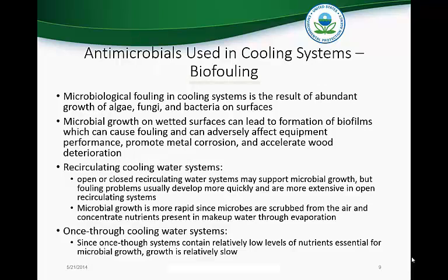We're going to talk a little bit about biofouling in this slide. Microbiological fouling in cooling systems is a result of abundant growth of algae, fungi, and bacteria on surfaces. Microbial growth on wetted surfaces can lead to formation of biofilms, which can cause fouling and can adversely affect equipment performance, promote metal corrosion, and accelerate wood deterioration.